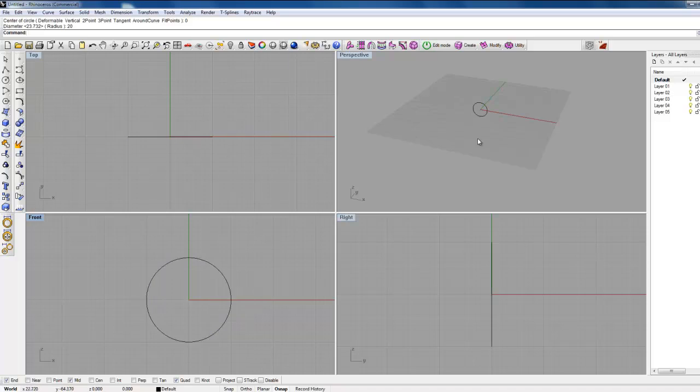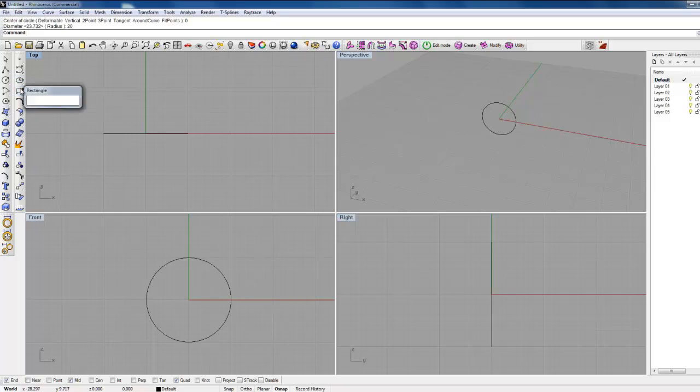Now what we need to do is make a cross section. If you can imagine, if you're sizing a ring, you cut a sliver of metal out and you turn that metal onto its side, the shape of that metal is going to be a cross section. So I'm just going to go for something really simple. If we go for a rectangle, and then if you click on it and hold your mouse down on it, it'll bring these flyouts out. You want to be picking that one there in the centre.